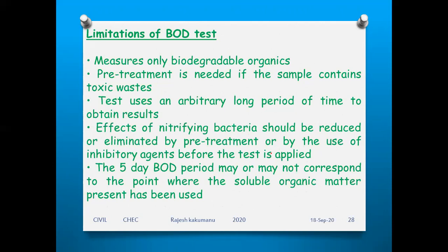And what are the limitations of BOD here? First one is it measures only biodegradable organics. So this test is used for biodegradable organics only, not for inorganic matter. Second limitation is pre-treatment is needed if the sample contains toxic waste.